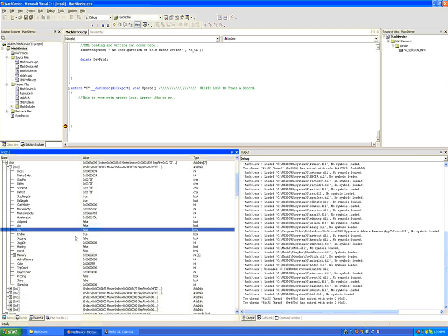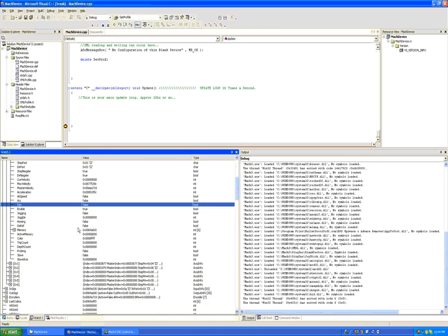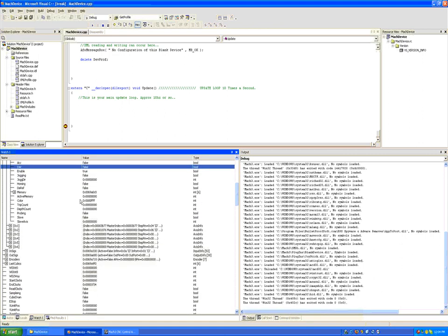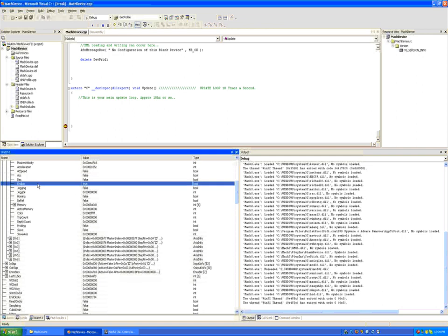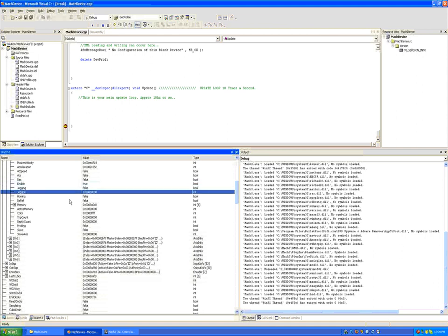You don't even try to follow these explanations, by the way. I'm simply giving you examples of what they do. You're going to have to play with a lot of them to see. Enable tells us if an axis is turned on or off. You could disable an axis, for example, just by setting engine axis, whichever axis, .enable to false. We have a jogging variable telling us whether the axis is jogging at the moment and a jog direction that it is jogging.